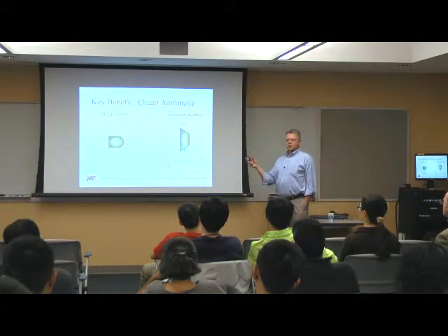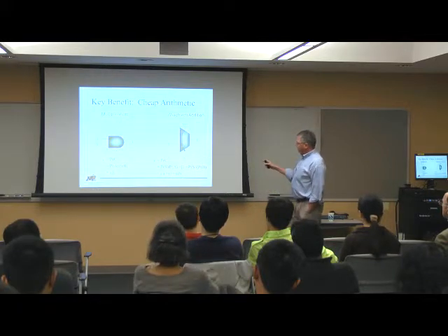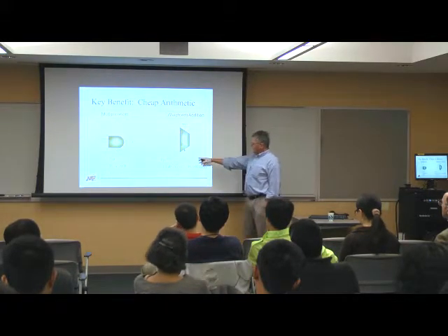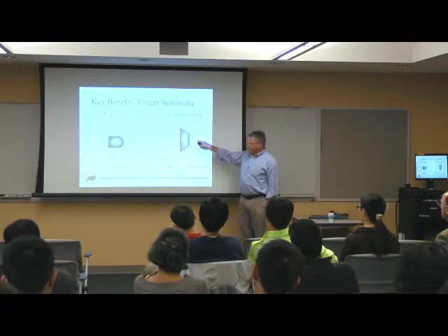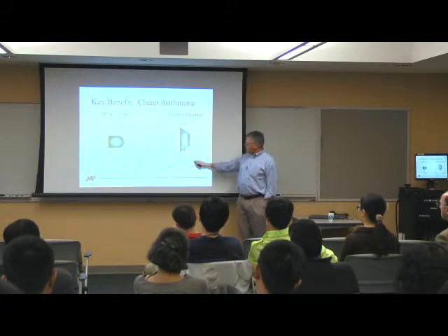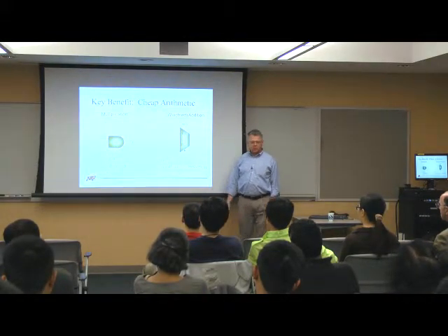Addition actually turns out to be just slightly more complicated than multiplication. If I have this multiplexer, the selector input chooses between A and B, so the probability of being a 1 on the output C is the probability of the selector being a 1 and A being a 1, or the probability of the selector being a 0 and B being a 1.